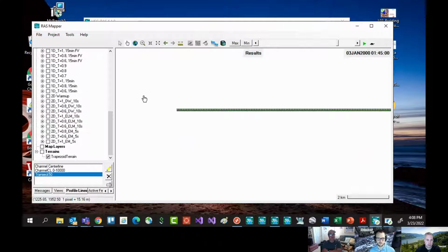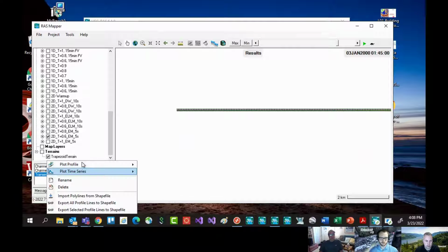So I've done the same thing using the EM. We'll go to theta equal to 6.6. By the way, I had to reduce the time step to make it work because, Gary, you mentioned it's a lot more strict with Courant numbers and not as stable as ELM. So I had to get the time step down a little bit to make this work. But let's see what we get here.